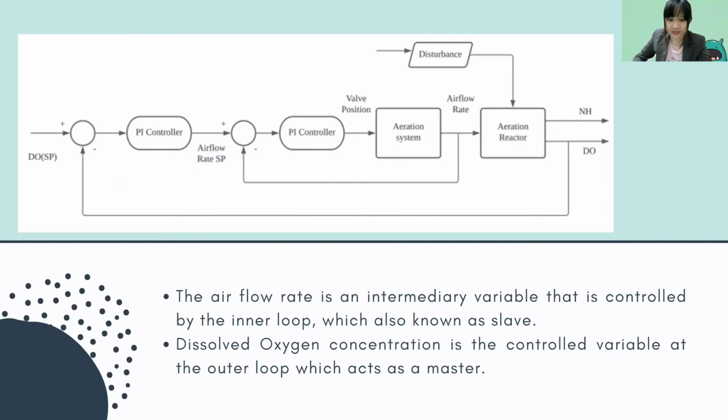rate. By implementing the set point of the dissolved oxygen concentration in the aerobic reactor, it enables the plants to operate in a condition where the ratio of the activated sludge process nitrogen removal efficacy to the energy required by the whole plant is improved. As a result, the system offers a comprehensive view as well as optimal distribution for control strategies.